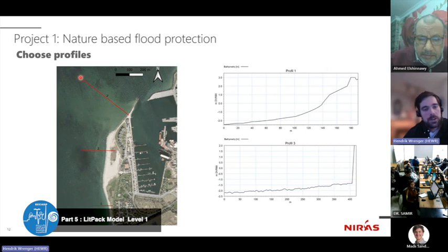And then nearshore, but that we actually discuss a bit further in my last project example, because it's a good example to discuss that component. But anyhow, we input the offshore wave conditions here, and then some nearshore shallow water wave transformation along the line is taken care of by the LitPack module FM, but no 2D effects anymore, right?